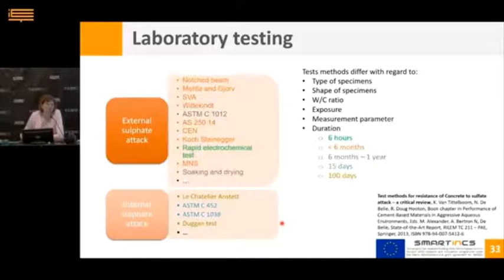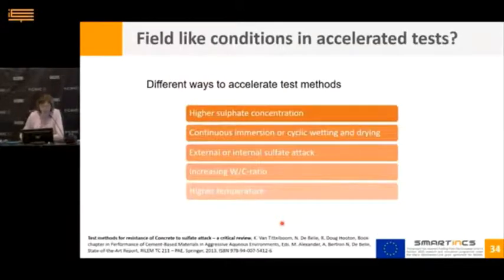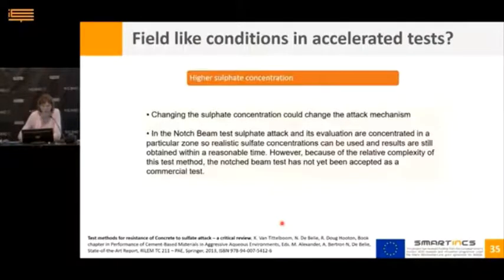Duration of the tests. So the tests are accelerated, but even though you see that it goes from a few hours up to 1 year, these tests that are mentioned over here. So still quite long tests that are proposed. And then to conclude, just a further analysis of some aspects of this. So first it deals with a higher sulphate concentration. So changing the sulphate concentration can change the attack mechanism. So we should be careful if we do that, or at least know what we are doing at that moment.